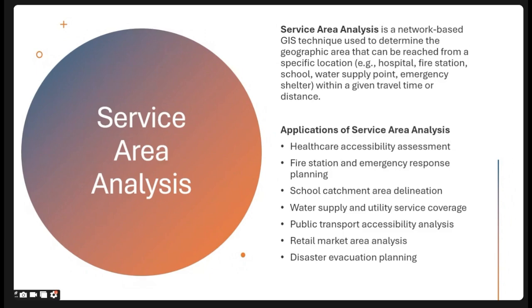So there are so many tools available in GIS where the user can measure distances or identify buffer areas, we can say, to get that accessibility constraint and to provide a realistic representation of the service coverage. This analysis is basically useful to evaluate the response time and ensure rapid emergency assistance for any kind of decision making process.